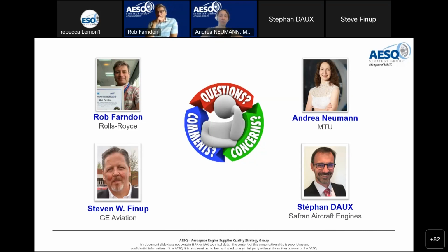Okay, another question in there is, how important is it to use software for DFMEA? Different schools of thought on this. The software will enable you to find and store and recall information quickly, right? But I believe wholeheartedly that the majority of the value inside any DFMEA is in the team interaction and the discussion of the priorities on the design. So if you've got bad team behavior and poor preparation, no amount of software is going to cover that up.